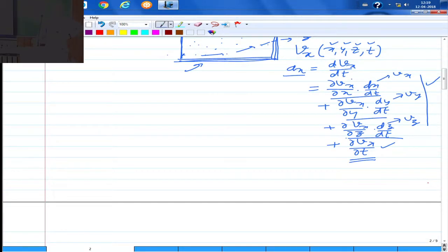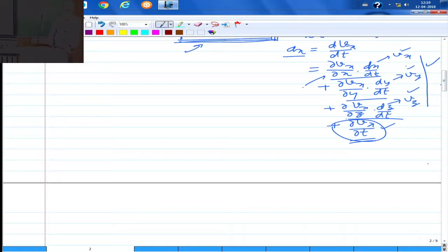Then another question was about when I had discussed one of the applications to a fluid mechanics problem. There we had said that these velocities are small, so the convective terms of acceleration can be neglected and only this term retained. But if these velocities are significant, then the convective acceleration terms are important and you'll have to consider them. Of course, then the problem becomes a nonlinear problem. So this is the difference between the Lagrangian description of motion and the Eulerian description of motion.